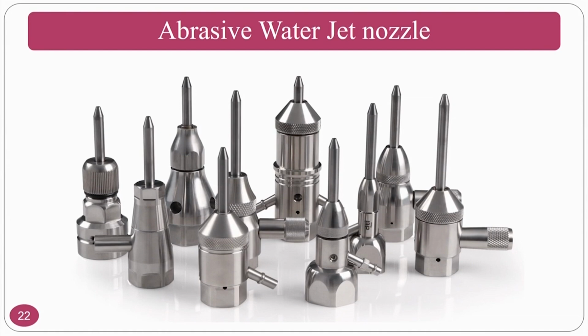These are the other varieties of nozzles where you can play with the stand-off distance. The stand-off distances are varied. If you go for smaller nozzles, it will be different. You can see in this particular nozzle, this is how the abrasives are fed. In some cases, the abrasives are fed here. In some cases you can feed perpendicularly. So, however you want, you can feed. So, there are multiple jets.